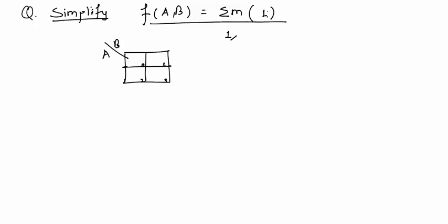This first combination has logic 1 value, other combinations have logic 0 value. So the first combination will have logic 1 value. Now in this K map we have only a single one. For this single one there cannot be a pair of 2 or a pair of 4, it will be a single. For this single we will write the expression for f. For this one a is 0, for this one b is 1, so it will be a bar b. This is the expression for this.